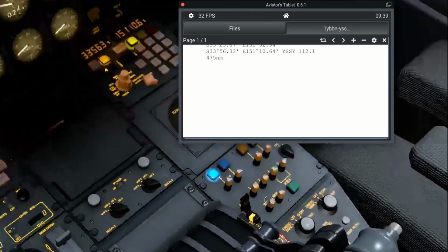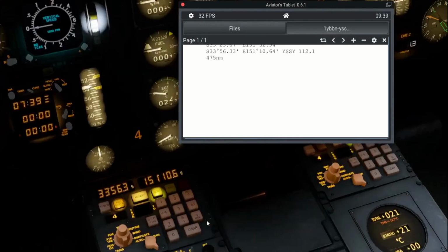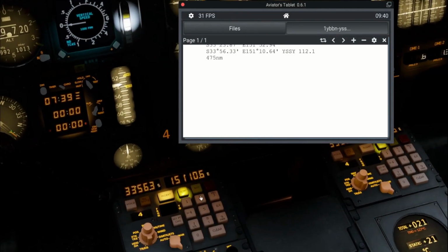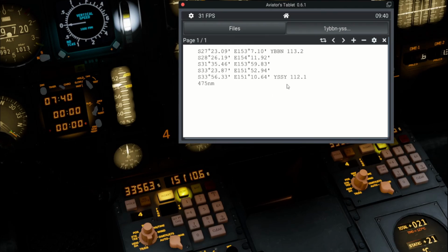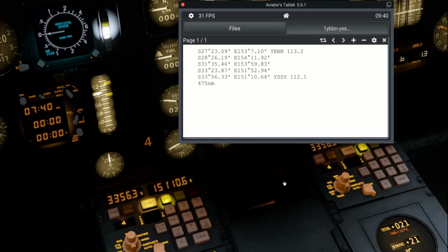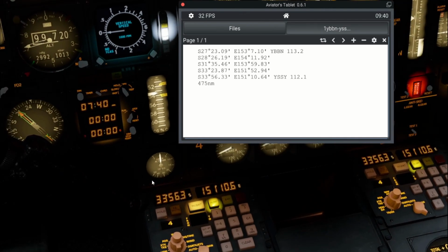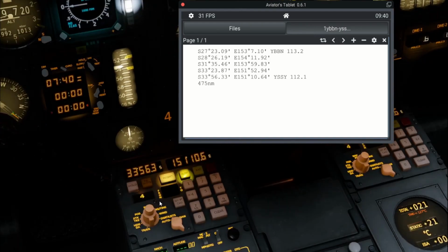Yes, we have a kind of alert. This is okay. There is a DME function. We can set a DME along the route to check and maintain good quality of INS precision or signals. But we will not do this because the flight is very long and we will not be degrading the INS properly. But we have to align that unit with the current position.